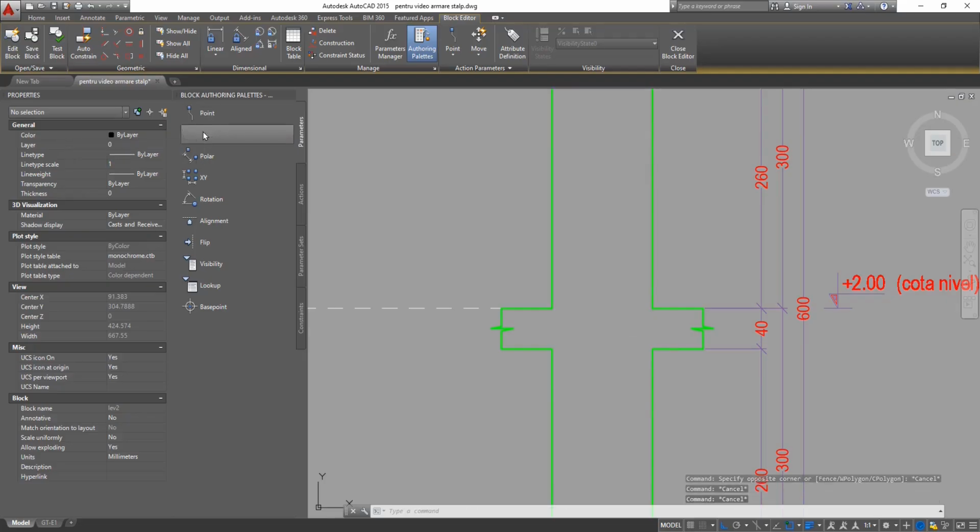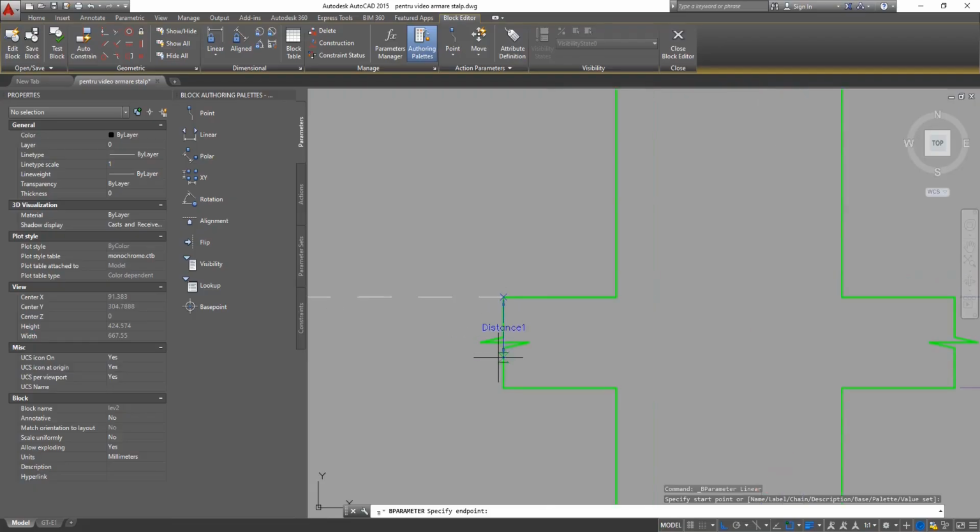So in the vast majority of cases, the beam will develop downwards, of course. So we're going to place the starting point of the parameter that will determine the height of the first beam on the top of the level, going downwards on the beam. Okay.